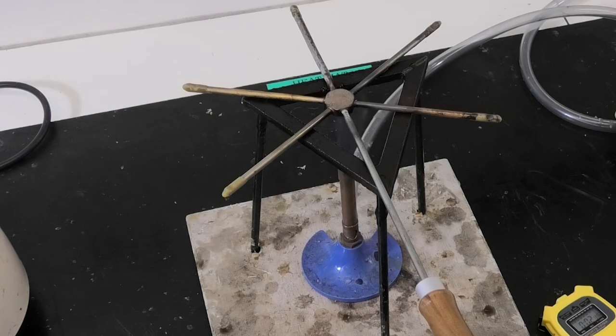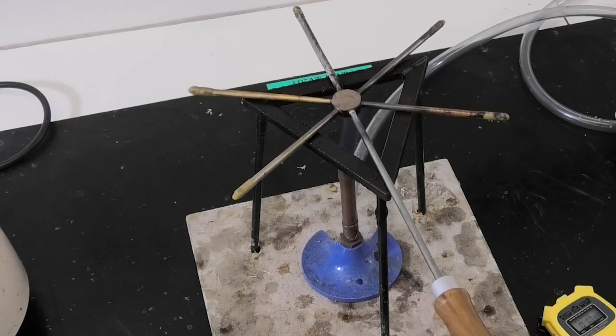Start the stopwatch at the same time, and we'll speed up the clock a little bit. In this bit of video, you need to note the time at which the wax melts on each one, so you might need to go over this a couple of times because the drips are hard to see. You'll find out the times at which each one of those wax drips occurs on each metal, and compare that with the thermal conductivity of that metal. You won't necessarily need to do the last one because it's just the order of melting specifically, but record the times all the same.